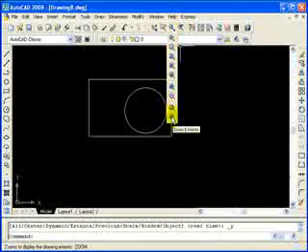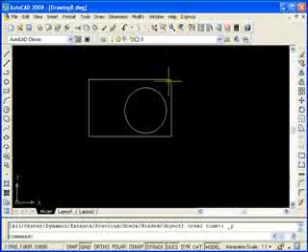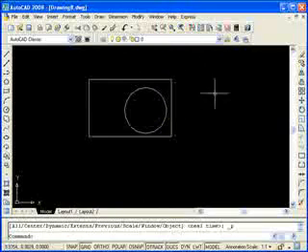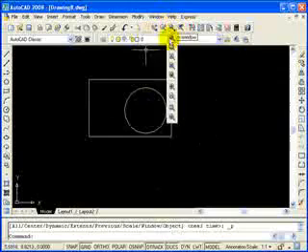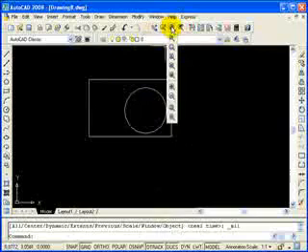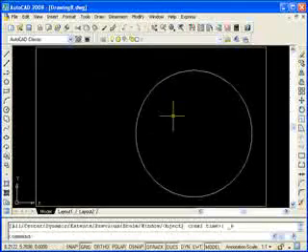The other one is zoom extents. Zoom window, remember, zooms to the extents of the drawing limits. Zoom extents zooms to the extents of the objects that are drawn. Okay. My grid, you'll notice here, is representative of my drawing limits. So when I zoom all, it's going to zoom to the extents of my grid, which are my drawing limits. If I do zoom extents down at the very bottom, watch what happens. It ignores my limits and it zooms to the extent of the items that I've drawn.